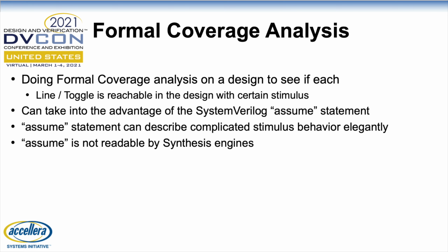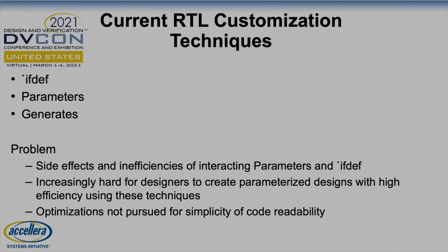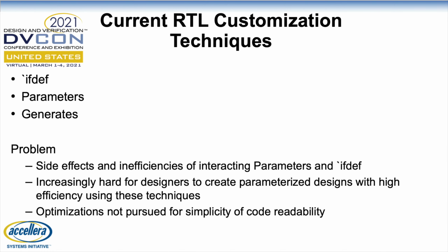And of course, this assume statement can describe almost any type of behavior very elegantly, very quickly. Unfortunately, the assume statement is not used by current synthesis engines. RTL designers have techniques also that can help them realize their designs as efficiently as possible. They have the SystemVerilog define, parameters, generate statements.